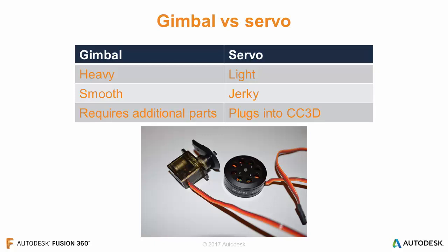So while we will get a little bit of jerky motion, we can achieve the same type of thing that a typical gimbal setup will require. However, we can do this without having additional equipment because we can send a 5-volt signal directly to the servo to control it without having any additional boards, IMUs, which are inertial measurement units, or any ESCs.